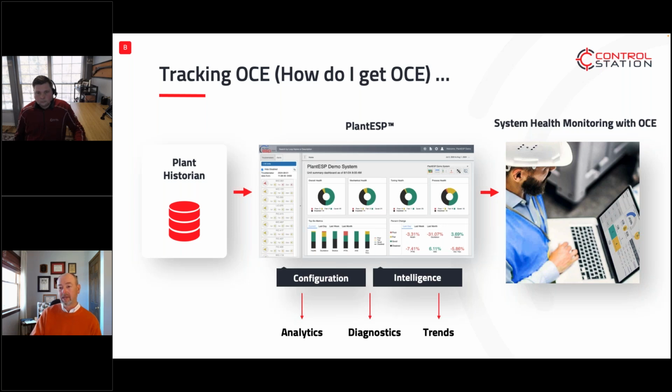So its job, through proper configuration and setup when the system is installed, is to be able to understand the different controller modes, and on a loop-by-loop basis to be able to say, well, this is normal for this loop, so let's not worry about that. And these are the abnormal modes of operation, and that's when we do want to pay attention. So that's a really good point.